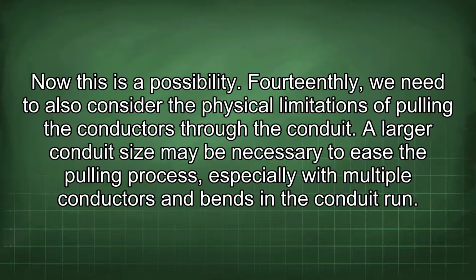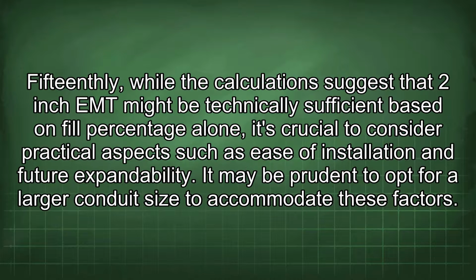14thly, we need to also consider the physical limitations of pulling the conductors through the conduit. A larger conduit size may be necessary to ease the pulling process, especially with multiple conductors and bends in the conduit run. 15thly, while the calculations suggest that 2 inch EMT might be technically sufficient based on fill percentage alone, it's crucial to consider practical aspects such as ease of installation and future expandability. It may be prudent to opt for a larger conduit size to accommodate these factors.